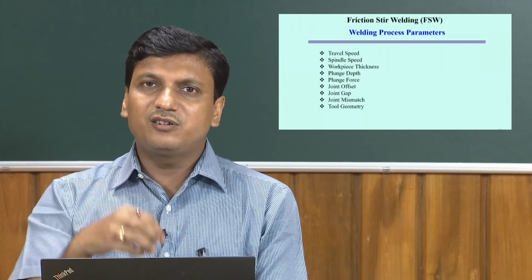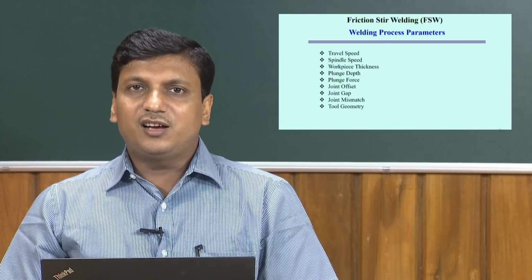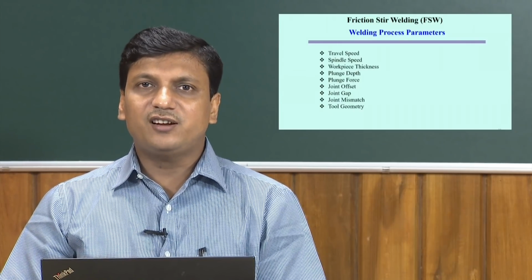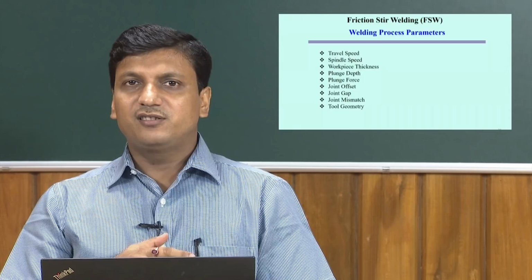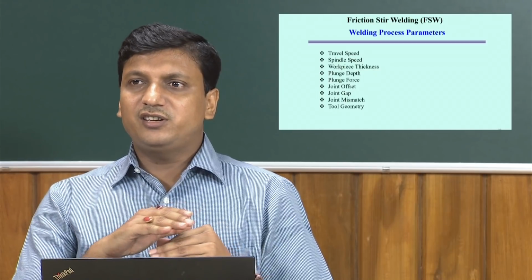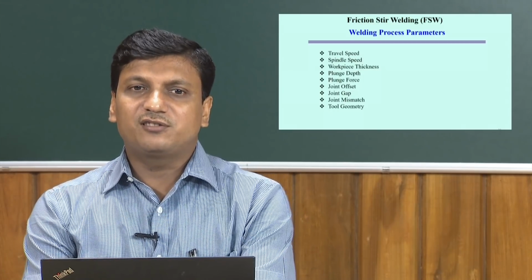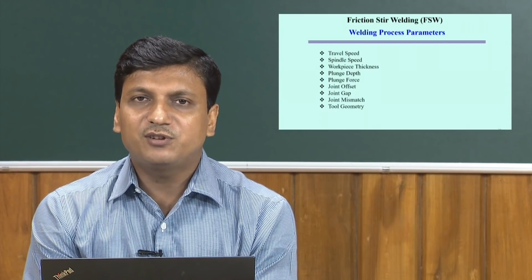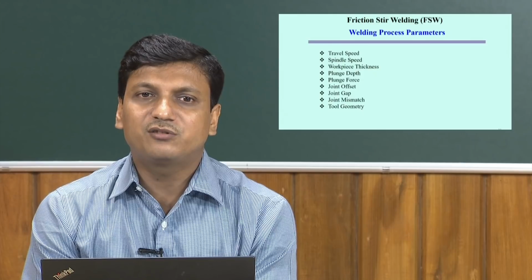So, that load is also an important parameter, such that during the process whatever force is exerted will maintain the steady state welding of the workpiece material. That force can be measured also, and it is one of the significant parameters in the friction stir welding process.